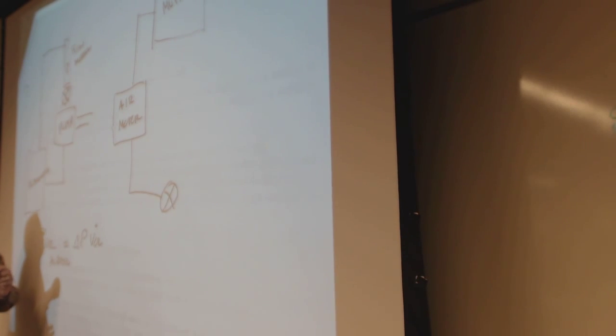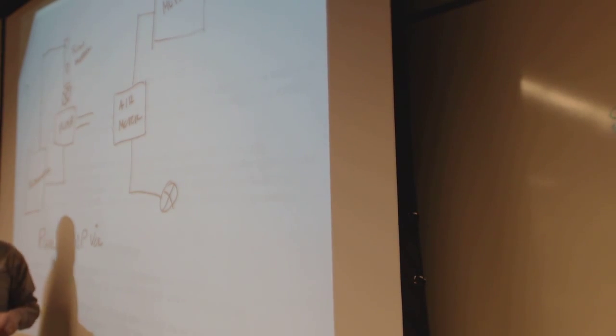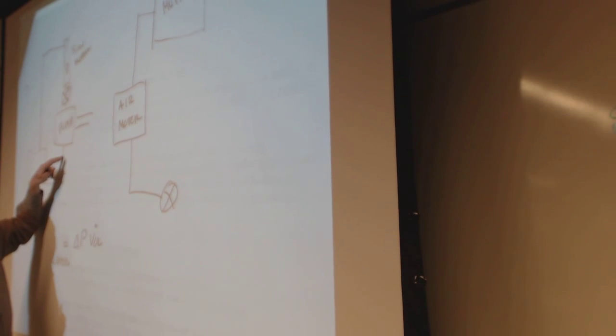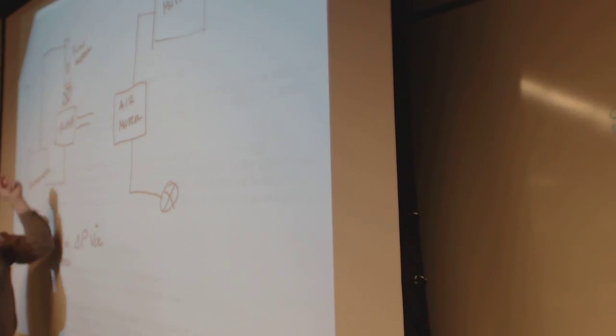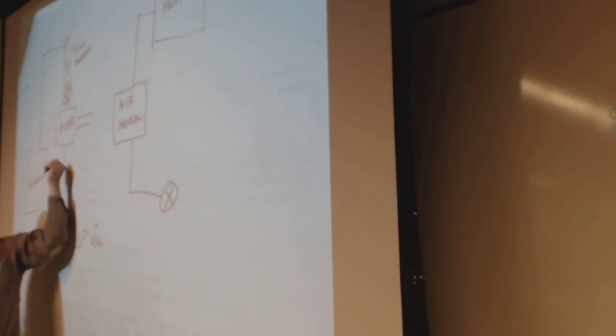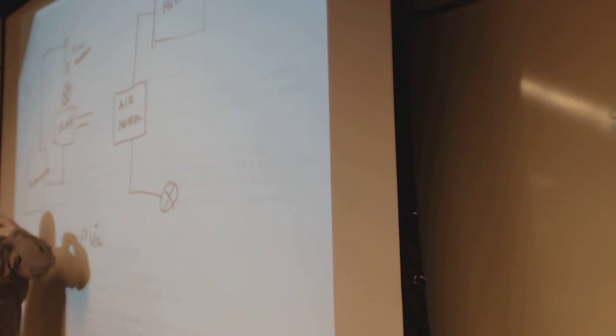It's sucking on this side, so we have to make sure we use the pressure difference, because this side can drop 1 or 2 or 3 or 4 psi, and if you're talking about 20 psi, that could be 20% of your total pressure difference. So we need to watch for that suction side. The difference in pressure is what the pump's doing. Any ideas why this might go from a neutral pressure to suction, basically negative pressure? Because you're pumping liquid out of the pump.